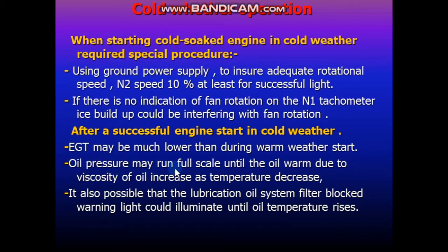Also, the oil pressure may run full scale until the oil warms, due to viscosity of oil increasing as temperature decreases. The oil pressure also, you will focus on that, it will not give us the reading as in warm weather. It's also possible that the lubrication oil system filter blocked warning light could illuminate until the oil temperature rises.